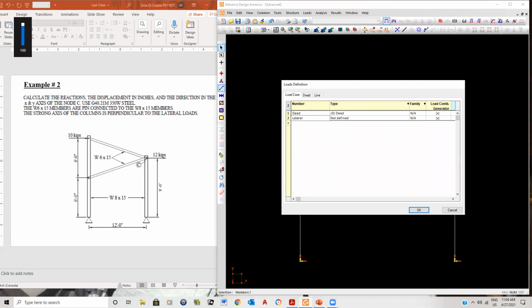Now this lateral load, believe it or not, can actually be caused by the cable itself. As a matter of fact, I've done this in my career where I had to design these structures, and believe it or not, the electrical engineer would actually give me the forces that these cables would impose on my structure, and I'd have to design my structure accordingly. Okay, and this is all given to you by the guys that actually manufacture the wire. So that would be a lateral load.